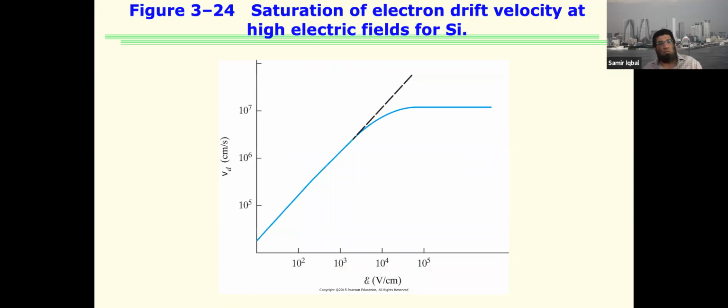All right, now one can say I can keep on ramping up the voltage and the average velocity can keep on going up. So we can have high conductivity, right? Because mobility was dependent on average velocity. But that's also not the case. There is a rollover in the voltage, rollover in the current, because the drift velocity becomes constant. It cannot go above a certain limit. So far in conductors, we say you keep on ramping up the voltage, the current will keep on going higher and higher. Electrons will start moving much faster.